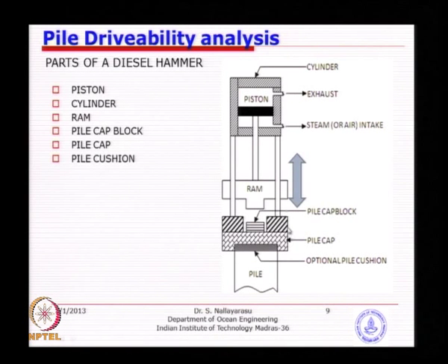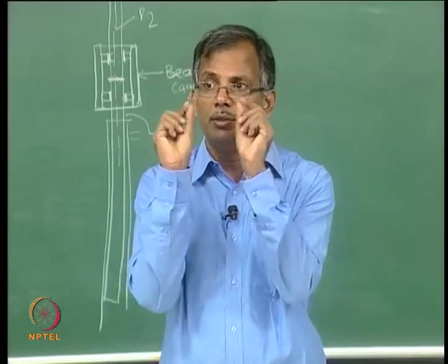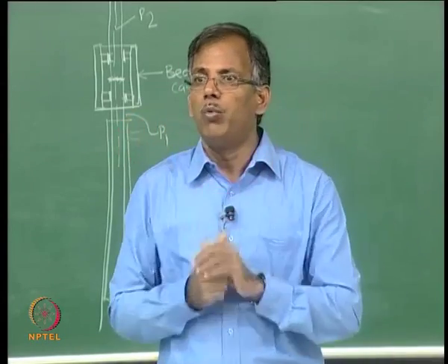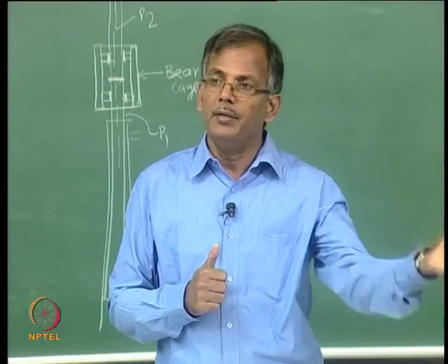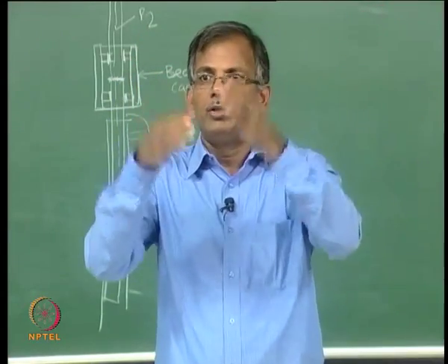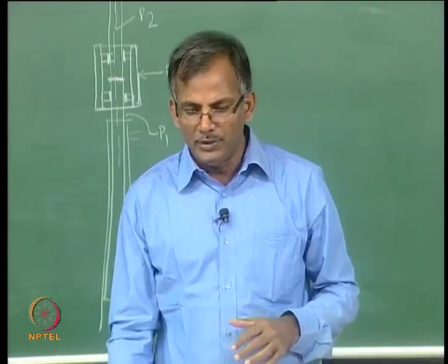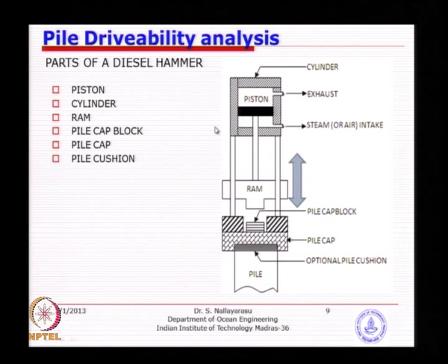You also see some of the components, basically an interface between the ram and the pile. We do not actually want to strike the pile directly, because you may damage the edge of the pile wall, because the next time you bring in another pile to be welded, if substantial damage is done to the pile, you may have to cut and resurface it. Edge preparation will take a lot of time. Of course, even otherwise, if you damage a larger portion of the pile, which is not very good,